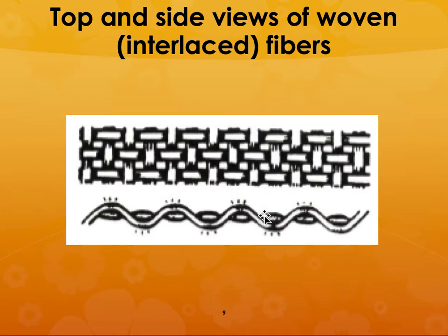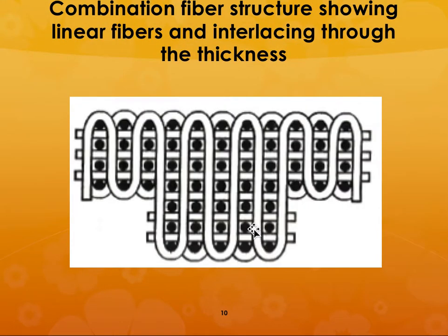One fiber tow goes up and down, up and down, and then you have the fibers in this direction. This would be called a plain weave. It is a straightforward weave: one weave going in the 0 direction and another weave coming in the 90-degree direction. So this is called the 0-90 orientation.